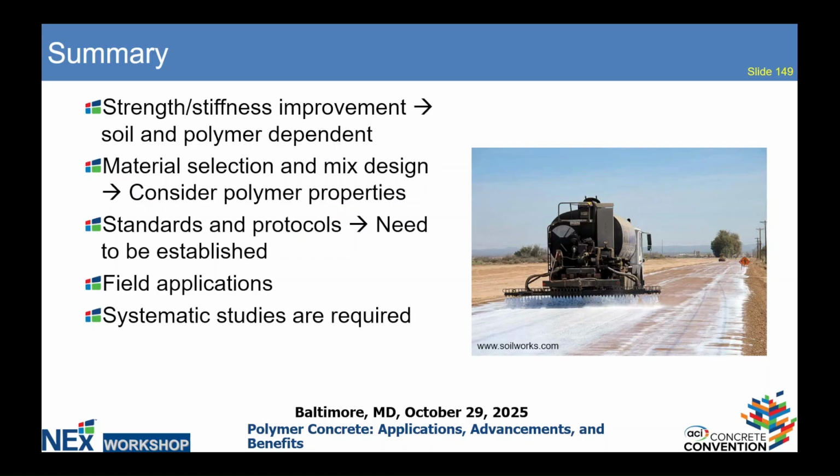We can see the polymers have the potential to increase the strength, however, it does vary a lot. It depends on the soil and the polymer type, which means we have to carefully select our material, and also the standards are much needed, field application as well.